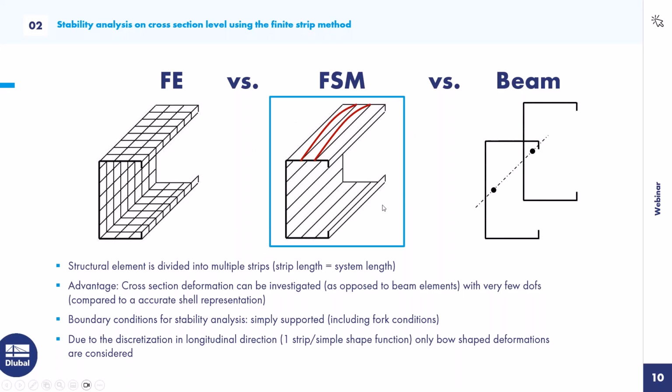And when we activate the finite strip method in the edit section dialog, a lot of these FSM members are generated, and the eigenvalue analysis is performed, and the eigen shape is stored, and also the critical bifurcation load is stored. And this happens on the go. So if we click it in the edit section dialog, it's done, and it finishes like 50 analyses in less than 1 second. So this is quite a nice advantage of this analysis method.